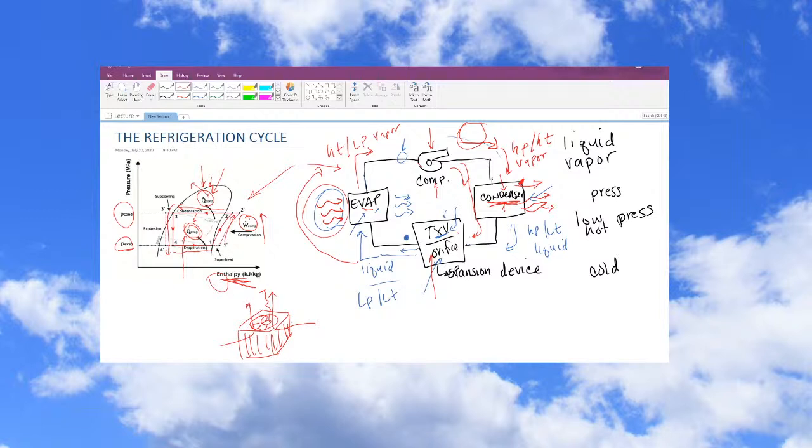So you have the fan moving air across your condenser, but if you look inside, you get a little X-ray vision in here. What you'll see is inside there's a little compressor in the middle, sitting there by itself. Sometimes they're tall and skinny if they're scroll types, and then sometimes they're flat and round like this if it's like a centrifugal style or a piston. Often there's not a whole lot of centrifugal AC compressors. I said that earlier, but I meant piston style. There's reciprocating pistons, and then there's the scroll or screw types like a supercharger. A lot of these vertical ones like that, and these guys are in here doing the compression of your fluid.